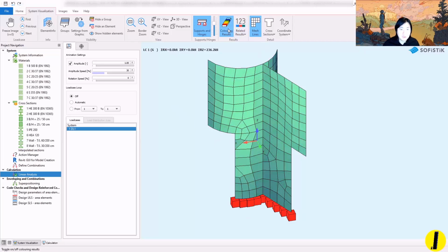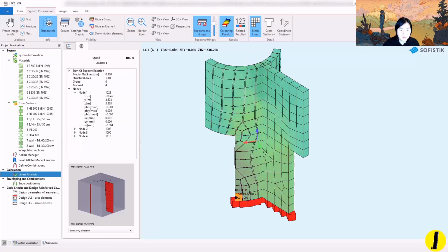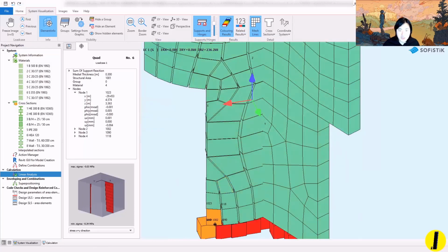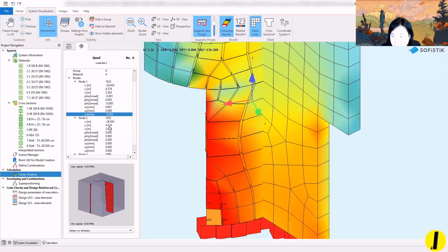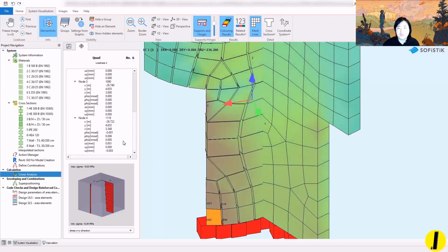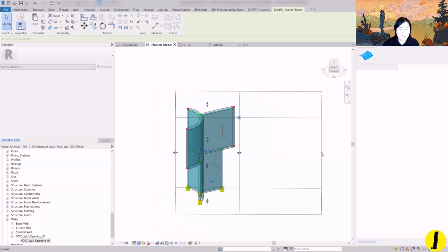Let me see the result in utilization, and if I look here, double click on this mesh here, and the deformation, if you look here, is really small. You can see there is no deformation here in this case. It's about minus 0.003 millimeter and so on. So this is not a big deal. Alright, so that works perfect, and I'm gonna move on to the next example.